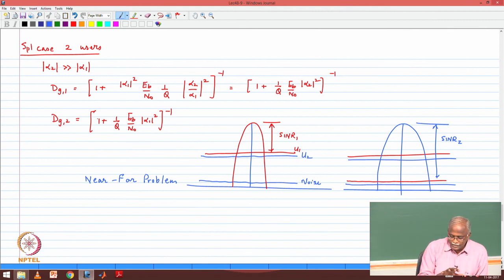It is tied to the notion of interference and power levels and spreading and despreading, all of that put together. But where does it actually creep in? When all of them are under ideal power control, it does not show up. But when one of the users does not obey power control, then it starts to affect all of the others except the one user who is not obeying power control.